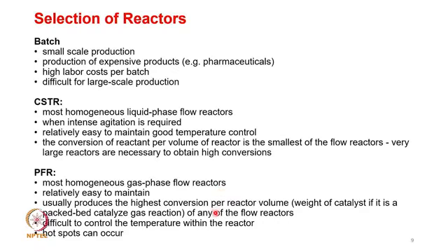And the difficulty is that there is no agitation or well mixing happening in the PFR, as the reaction happens when a front moves from inlet to the outlet. So, as a result, the temperature control within the reactor is not easy. There is no means by which you will be able to do good temperature control. As a result, hot spots can occur inside the reactor.